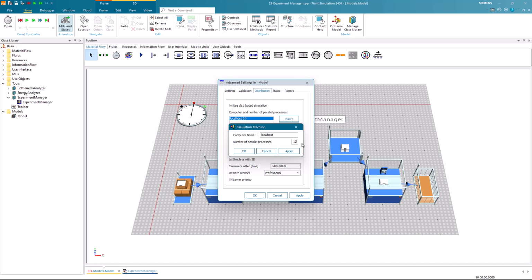However, it is important to note that using distributed simulations is not always advisable. For short experiments, the overhead of starting multiple application instances and running the simulation may result in longer overall execution times compared to running it in a non-distributed manner. Additionally, performance does not scale linearly with the number of cores. Using 12 additional cores will not necessarily yield results that are 12 times faster.